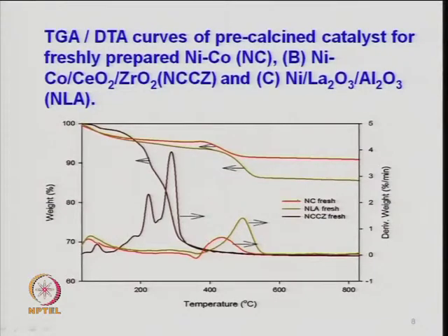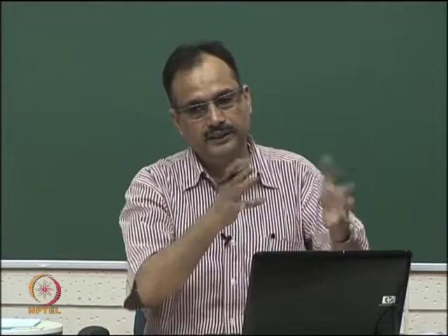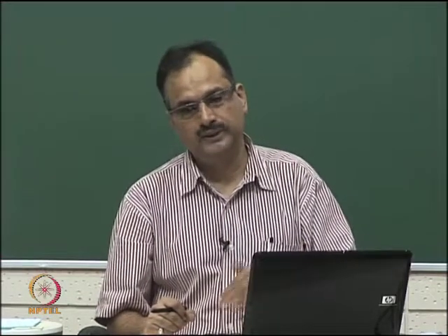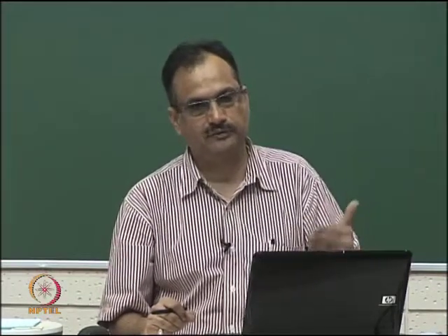From catalytic point of view, again we get similar information, that is you have a catalyst which is precalcined, right, something like a calcium carbonate itself may be a precursor for catalyst, right, support material, calcium nitrate, it can be also a support material. Same thing for other like nickel nitrate, if you have in your catalyst precursor. So, after you have done the initial preparation part, the co-precipitation method, Sol-Gel method, wet impregnation method, right, and you have done the drying or aging for 24 hours. So, now we say that calcine it, right, where you get the definite phase.